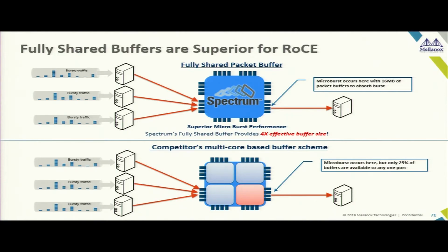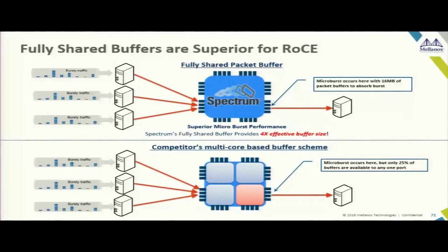What it means is, when people started designing Ethernet switches, you started increasing the number of ports. Now it's very easy to design a tiled architecture where you design a tile of 8 ports and then replicate those tiles in silicon and create a single package out of it. There will be minimal or no interaction between the multiple tiles, but there will still be a common forwarding table which makes sure that if data is coming on this tile and wants to go to that tile, it can be routed. But this kind of architecture presents a very big bottleneck in HPC systems.